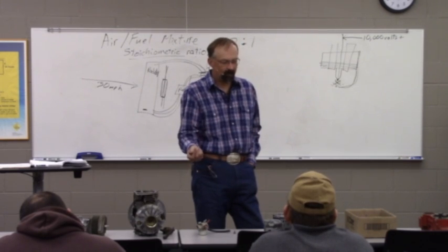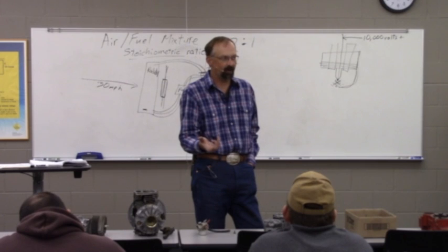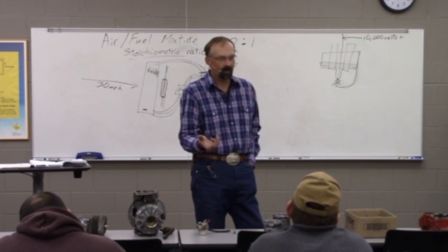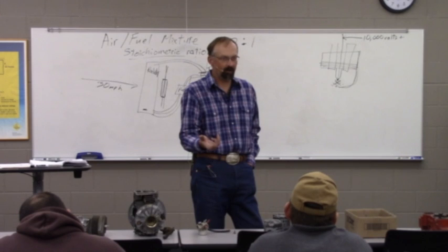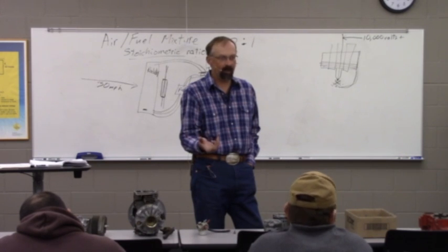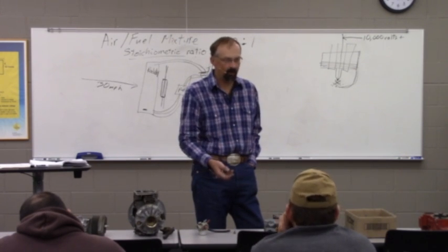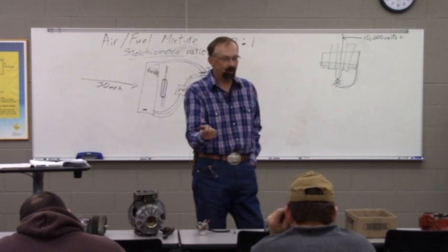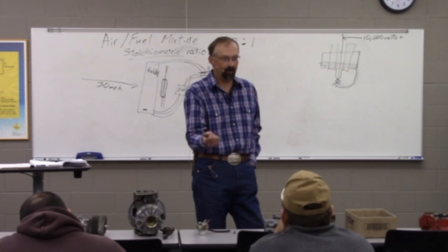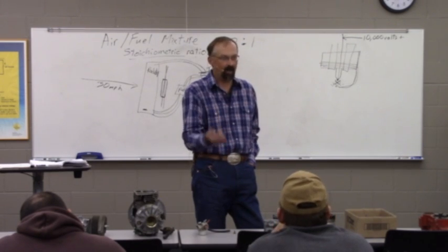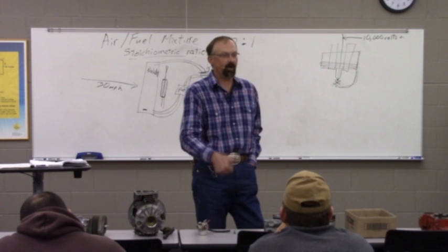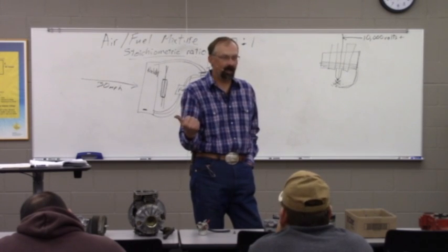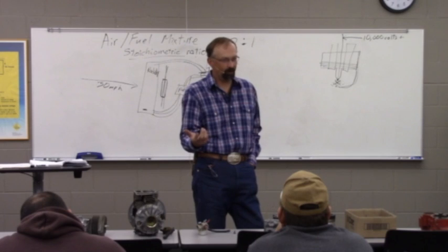But even with the T6, in most cases, and especially on the engines that have the exhaust gas recirculation, we're seeing that oil just be so contaminated by the time you get to like 4,000 miles. The oil still has good lubrication, but it's black as the ace of spades, and if you test strip it, it's got a lot of acid in it, and you're wanting to change it to get the contaminants out of your engine, not because the oil's really broken down.